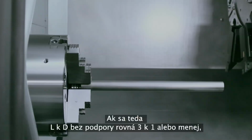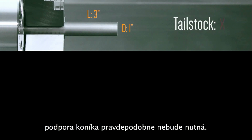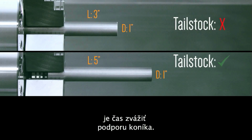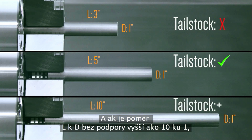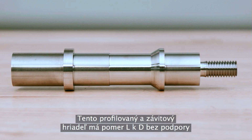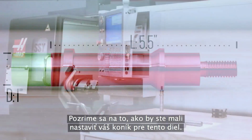Once you've exceeded an L to D ratio of 10:1, parts become so flexible that even tailstock support may not be enough. So, to summarize, we recommend when unsupported L to D equals 3:1 or less, tailstock support is probably not needed. When a part's unsupported L to D ratio is above 3:1, now it's time to start considering tailstock support. And when unsupported L to D is over 10:1, we'll definitely need tailstock support and maybe something more, like a steady rest. This profiled and threaded shaft has an unsupported L to D that's beyond what is typically possible without a tailstock. Let's look at how you'd set up your tailstock for this part.